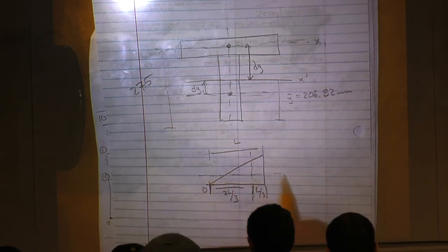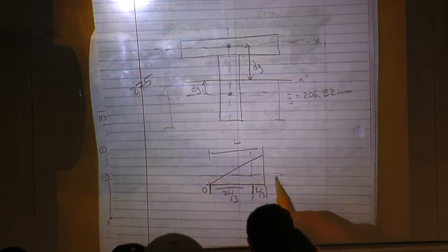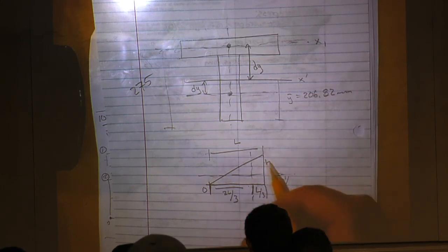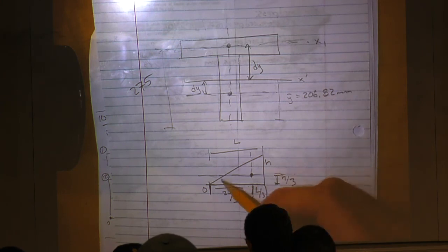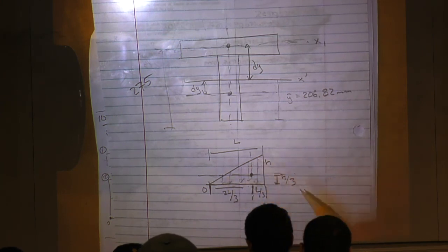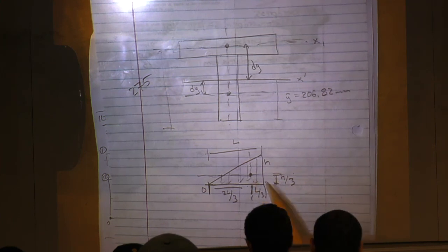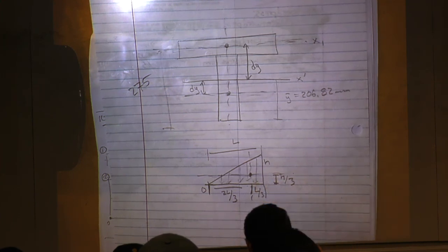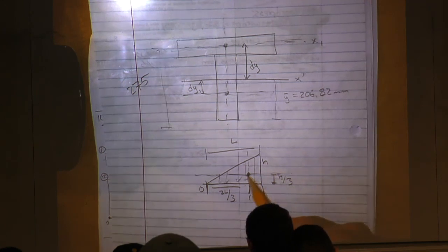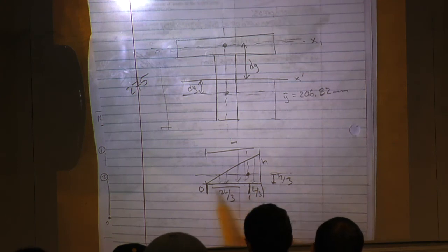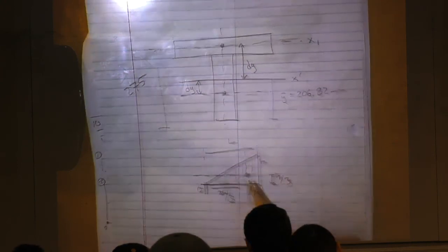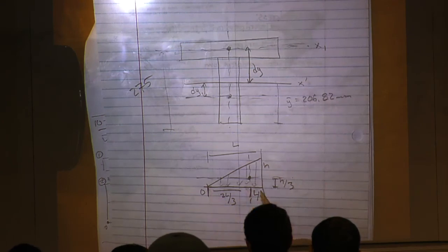And likewise, in my wider side, a third of the height, we'll call it H, H over 3 is where it's located. And the same thing goes for distributed loads, because you're just adding forces in here. So in a distributed load, the height is a force. So you wouldn't consider the y component something that it's pushing against on that side. So it would be the large side.